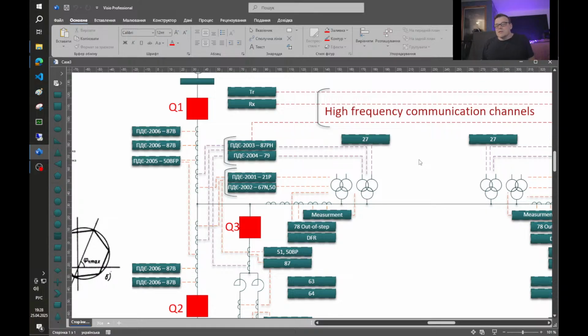about single phase auto-reclosing by itself. As you will see, at such a high voltage level, the three-phase trip is more stressful to the equipment than single phase, and three-phase trips can also cause swings in the grid, like any big system events. So for a lot of reasons, it's better to just trip one phase.